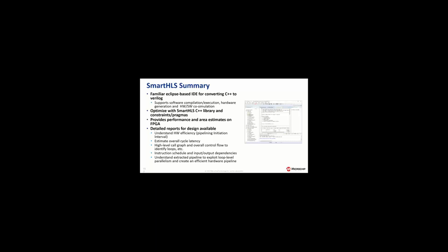That's the bonus. It's down to where you put the pragma. One key point to remember is that as you're looking at your code, it will implement whatever's underneath that C++. So depending on where you put that pipelining function, everything that's included in that might be expanded into hardware, and you might not want that. So you've got to be careful where you place that pipelining function.